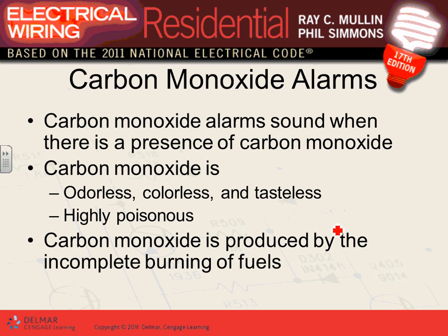You don't want nuisance alarms, but hopefully you're there. But if you're worried about fire in the kitchen, it's not required, but for more protection, you can stick in a heat detector. By that time, obviously, the kitchen might be engulfed in fire, but at least it alarms you. You know what I mean? So, can you put a smoke detector in a kitchen? Yes, you can. It's not recommended though.